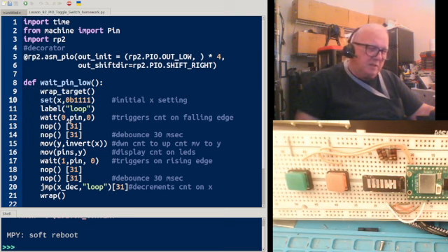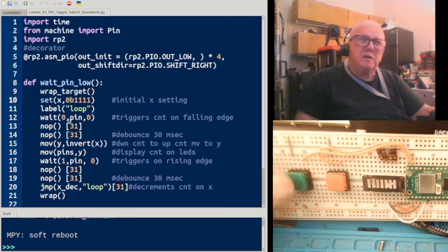And I noticed if you set this as 1 and this one at 0, you get a whole button push before it activates. So I switched it around, and as I push the button, it activates on the upswing. If you notice, as soon as I let go, it starts to go. What was happening is I was going down, and I was getting a whole cycle before it would start counting.